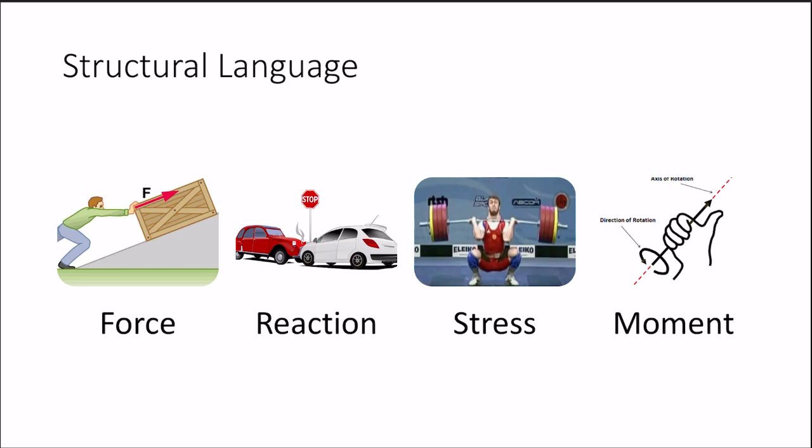Reaction, the opposite pushing force with the same magnitude but different direction. If a man stands on a floor, the weight of the body will produce a downward force into the floor. The floor reacts to this by pushing upwards with a force of the same magnitude. This upward force is called reaction. Similarly, a wall or column supporting a beam will produce an outward reaction as response to the downward force that the beam transmits to the wall. And a foundation will produce an upwards reaction to the downward force in the column or wall that the foundation is supporting. That is reaction.